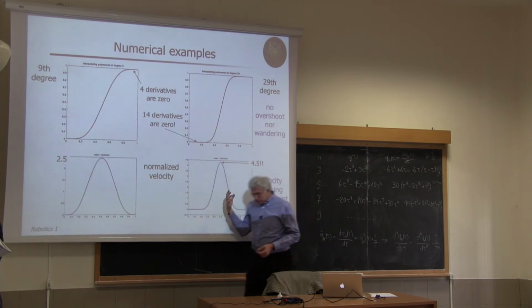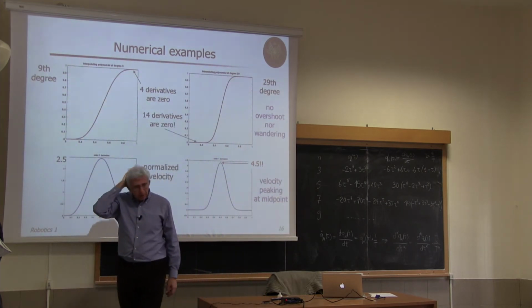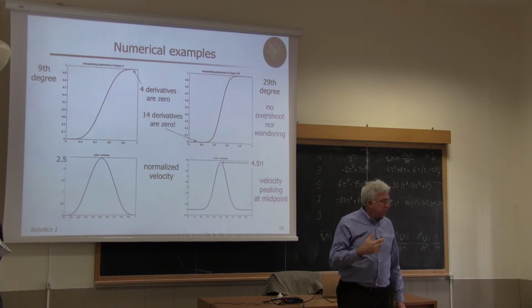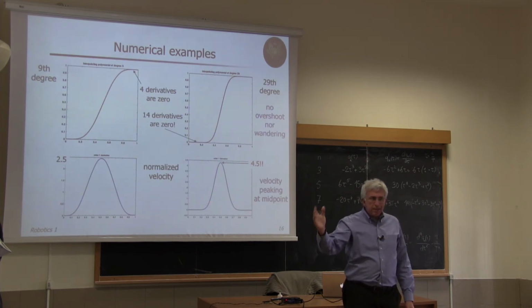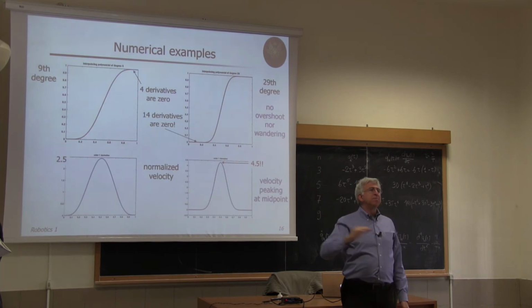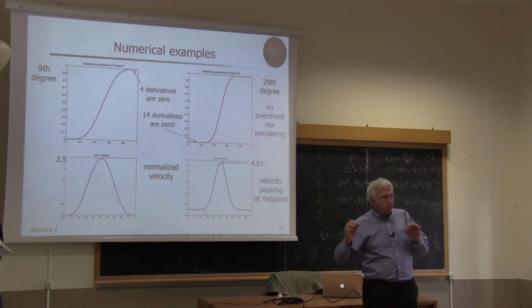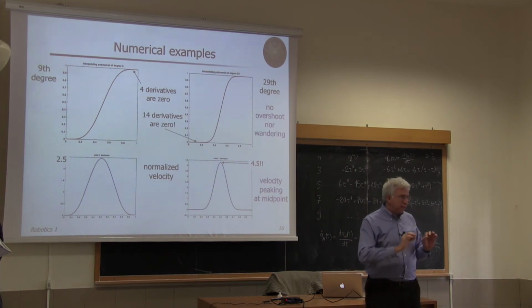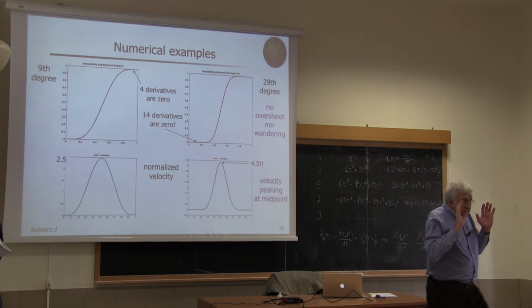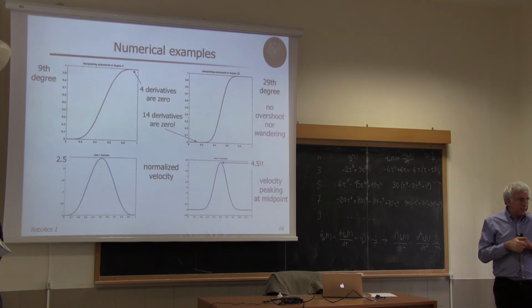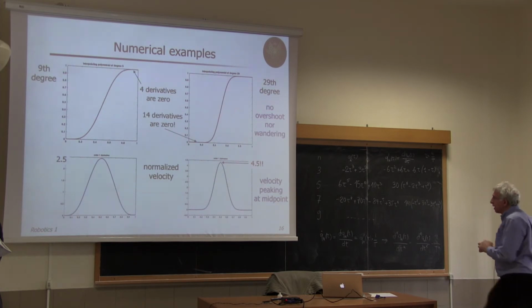Okay? Such kinds of polynomials are used, for instance, when planning trajectories for flexible manipulator arms. When you have flexible links, if you give a step input to those systems, they will start to excite all vibration modes. So they will start to vibrate wildly. So you try to start very smoothly and reach the end very smoothly. And this is not guaranteeing anything, but in practice it's very convenient to not excite higher order frequencies of vibration. Okay? So this is why this is of interest.